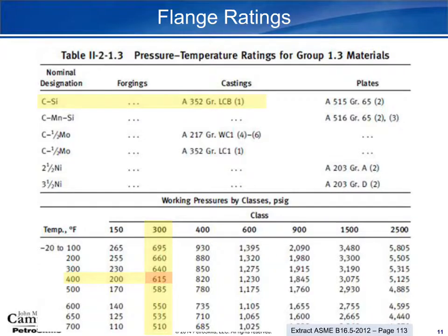When we start looking at stainless steel flanges, again, we see different allowable stresses, and the difference between a low-carbon stainless steel flange and a regular carbon content stainless steel flange makes a significant difference in these tables as well. So be aware that these tables exist when you're making specifications on your flange materials.